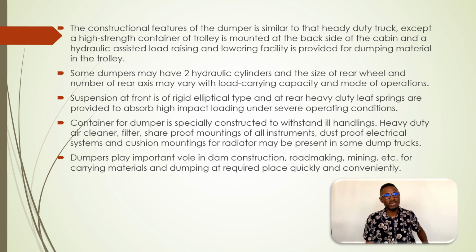Some dumpers may have two hydraulic cylinders, and the size of the rear wheel and the number of rear axles may vary with load carrying capacity and mode of operation. Suspension at the front is rigid elliptical type, and at the rear, heavy duty leaf springs are provided to absorb high impact loading under severe operation conditions.